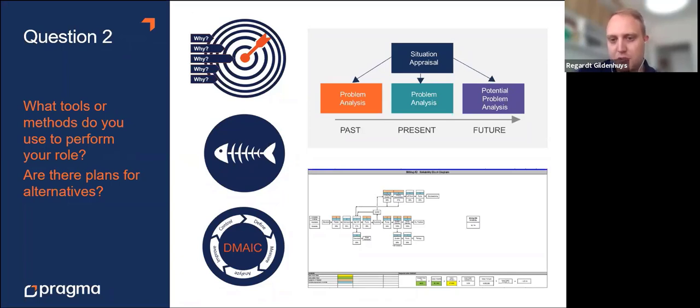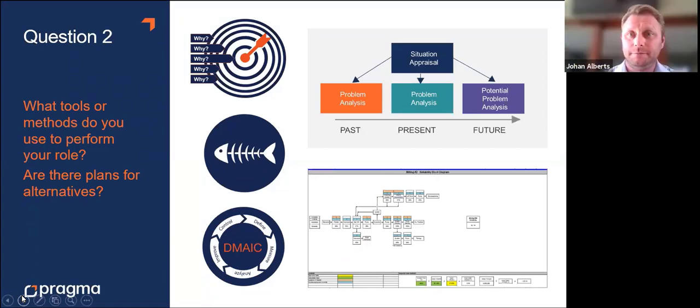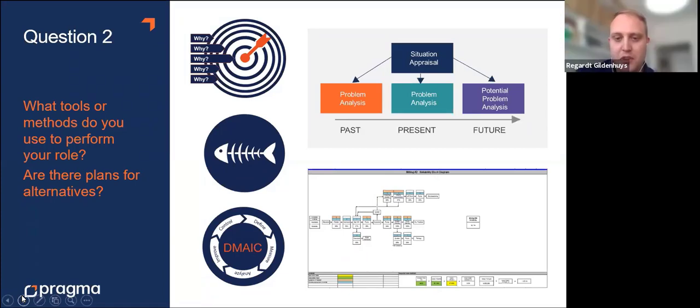You can first of all do it at the start of a project before any ground has been broken. Draw up your entire project in your reliability block diagrams, run your simulation, see where your possible bottlenecks are, see where you can possibly have a high risk area in terms of failures, so that you can solve those problems before you start spending any large capital. Exactly. And from the other side, how I'm currently using it is with an existing plant.